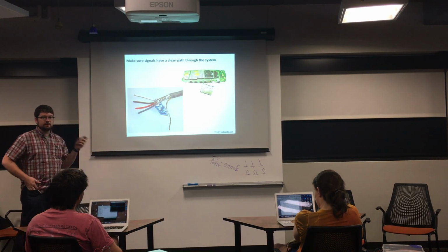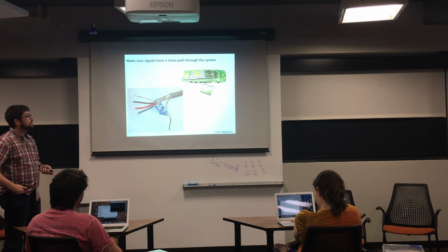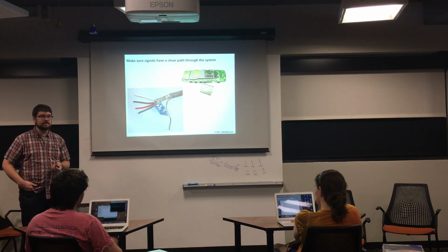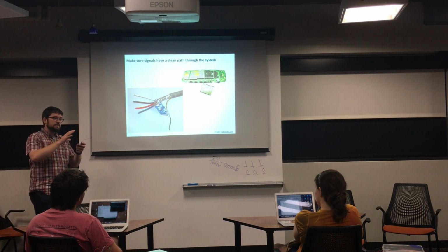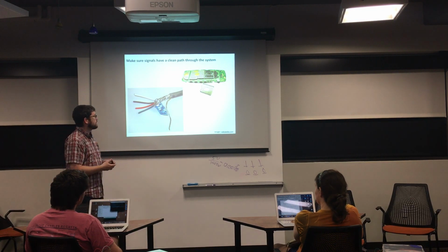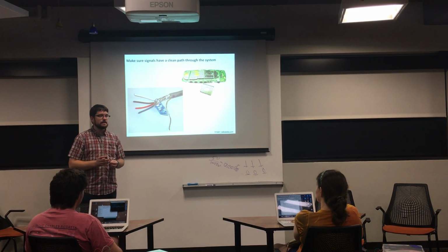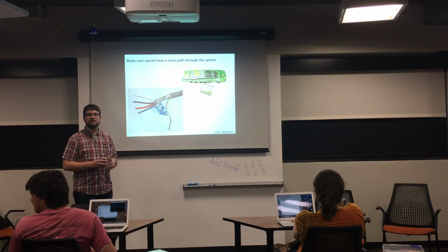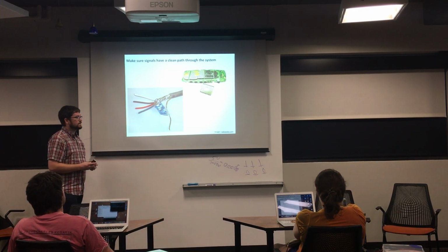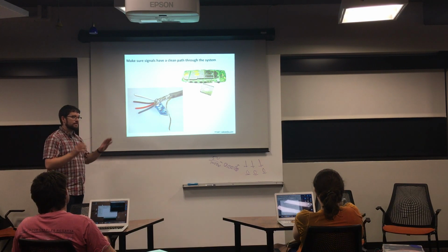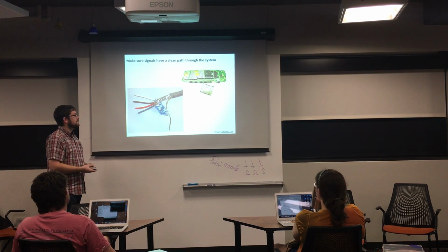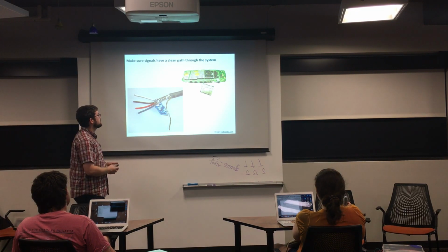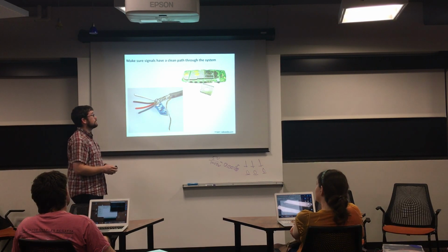Another big problem when you're doing data acquisition is signal integrity. Folks in our lab are familiar with this. If you've ever ended up trying to wrap some kind of pressure vessel or some kind of system in aluminum foil to try to get a clean signal, you're dealing with a signal integrity issue. It really happens. I've seen at very sophisticated facilities, people still having rolls of aluminum foil and trying to wrap connections to shield them. It's not something you want to do.